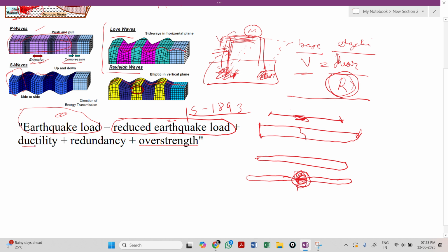Next, ductility. Right now, I've explained how it works. I've taken an example of a chalk and a steel member, a rubber band or maybe a steel member. And you know at one point of time, it will resist as much as possible. Ductility is the ability of a structure to deform without collapsing. In IS 13920, there is a ductility required. Whatever ductility is required is given in that. In upcoming classes, I'll be explaining that too. So IS 13920 is the other code book.